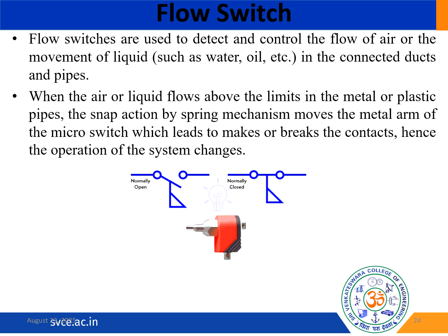There are some similar applications. We'll be using flow switches in HVAC systems to monitor airflow in ducts, and we'll be using flow switches in industrial fluid control, managing coolant or lubricant flow. It can also be used in water treatment and irrigation. So it can also ensure proper distribution and safety. Flow switches are essential for automated control. It can also be used for safety interlocks and process optimization in fluid handling systems. So these are the basic workings of flow switches.